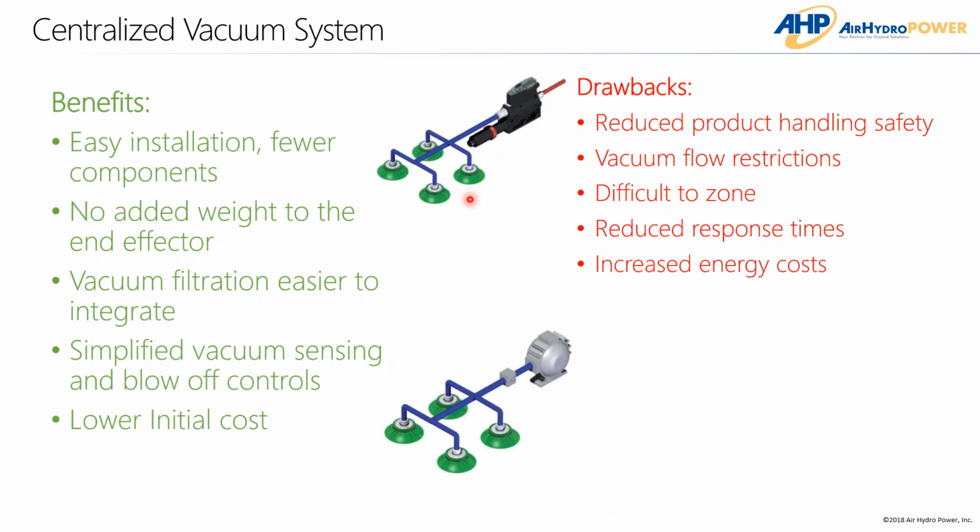And increased energy costs. So all of this adds up to that. Any leaks in this system, you're going to be losing energy there, losing compressed air costs, and a lot of times these are oversized. Both of these systems are to basically make up for any leaks in the system, or just all of this volume that needs to be evacuated. There's kind of a necessity to oversize it, and so that all adds to energy costs.